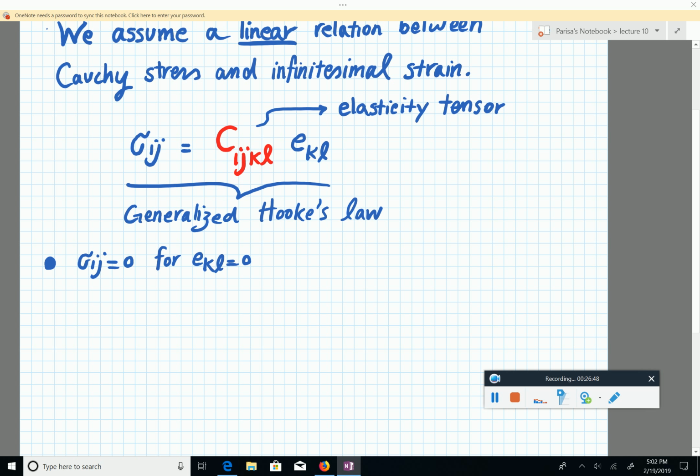Well, it's just, I work with composite materials, and sometimes you can apply pre-tensile stress to the fiber and then release it after you set it in the matrix, and it'll apply like a constant compressive load, for example. So you take that as your reference configuration, but you have a predefined compressive stress and everything. Exactly. So you have some sort of, can we call it a residual stress? Yeah, I was trying to do that.